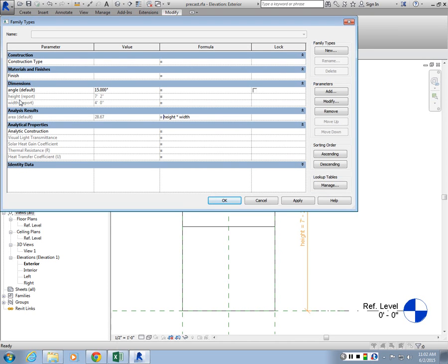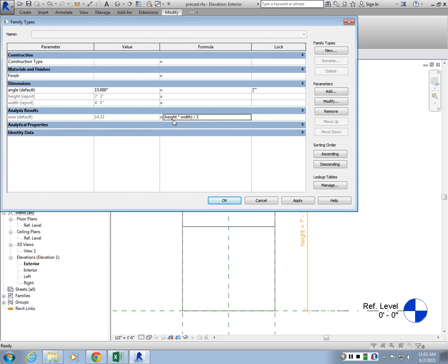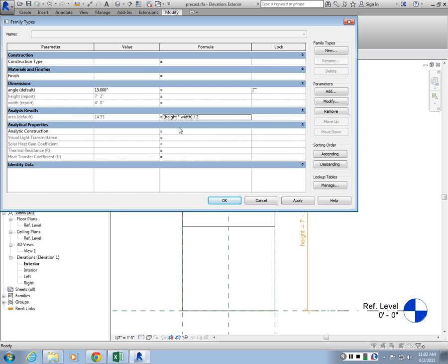So whatever those custom divisions are, each of those panels are going to have a custom area. And you can even add parentheses here and further customize it, right? I can divide it by a number, multiply it by a number. I can normalize it if I wanted to. Let's keep it the way it is now, like height times width.